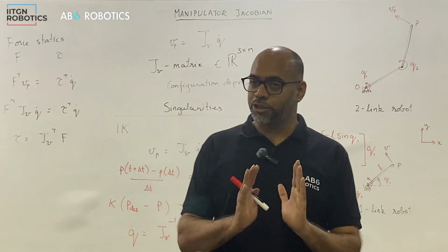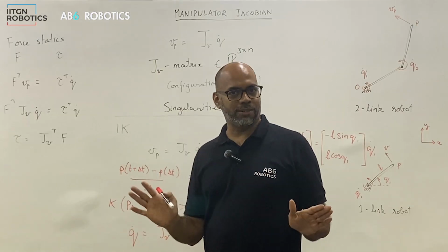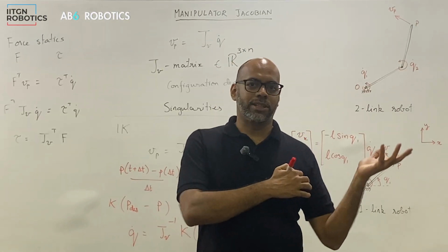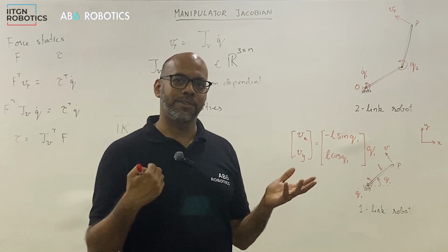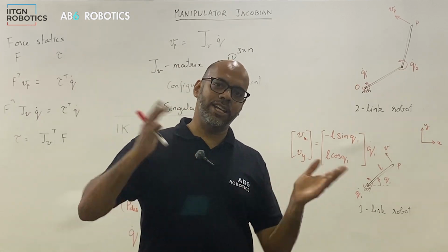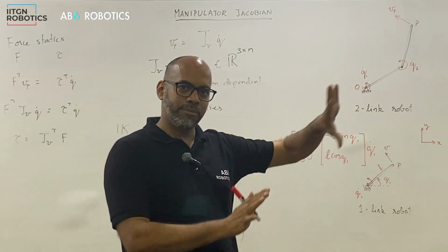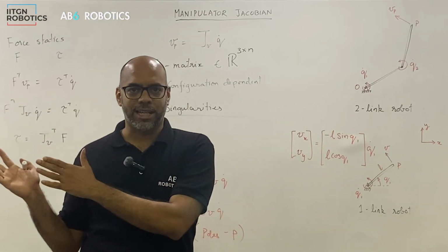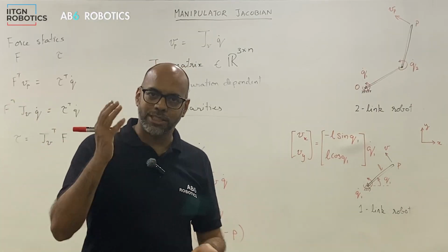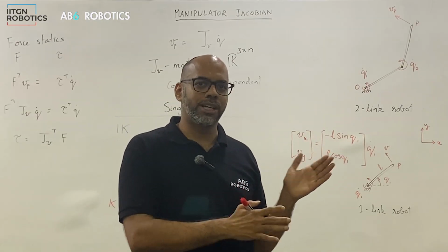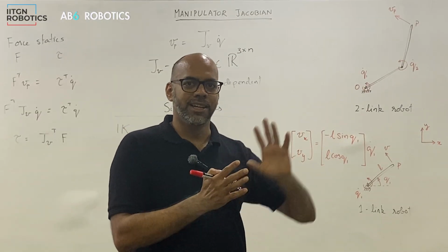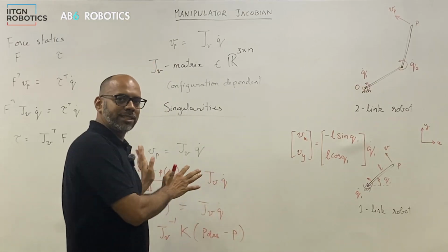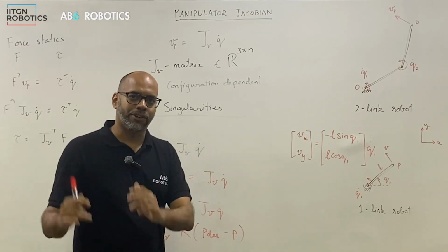The derivation of Jacobian is another story. We will not cover that here. But based on the DH system, there are standard ways to derive Jacobians for any robot as long as they can be described within the DH system. And there are some good derivations explained in various sources. There are also subroutines you can find directly to do that because it is so standardized once you start with the DH system. But that is not the point of this discussion, and I would leave that for a separate discussion.